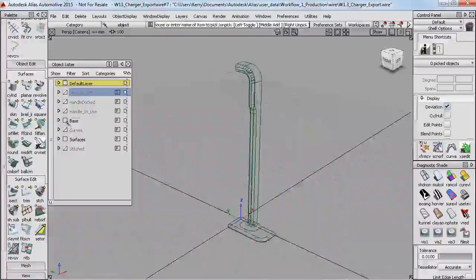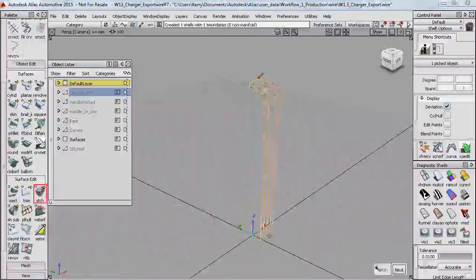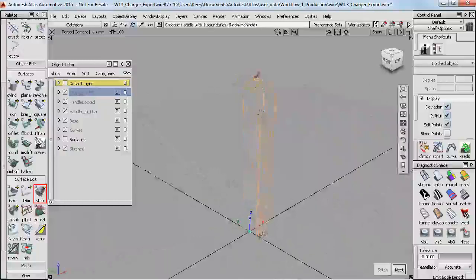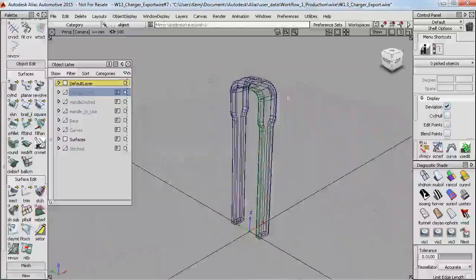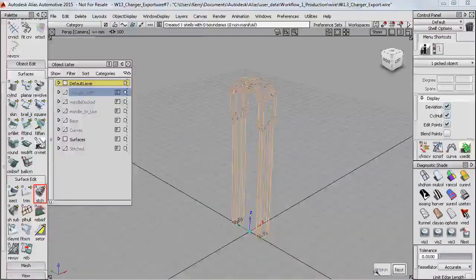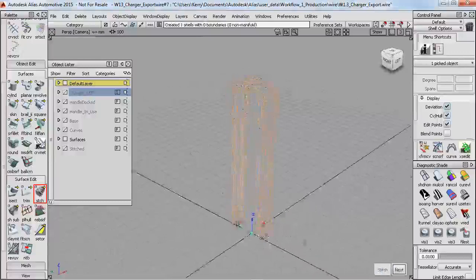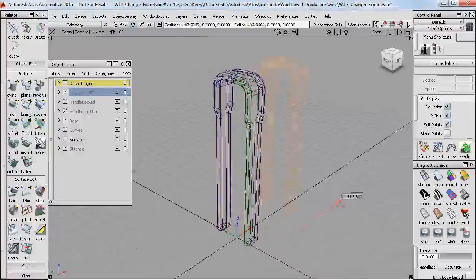So if I'm ready to get this prototyped, then I'll need to check that the mirrored sections will stitch. So I'll do that one, and that's fine down the centre line. And then I can mirror it in the other direction to complete the model and just check that that's stitching as well. So this is ideally what we're aiming for, all orange edges, which means it's completely solid.